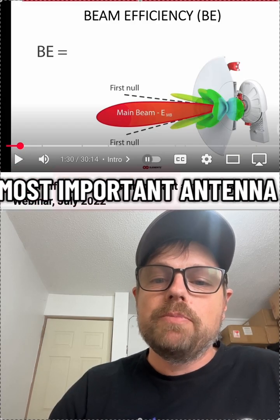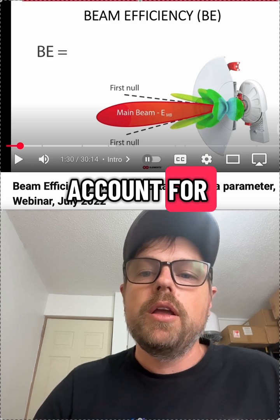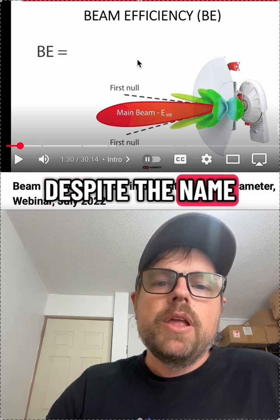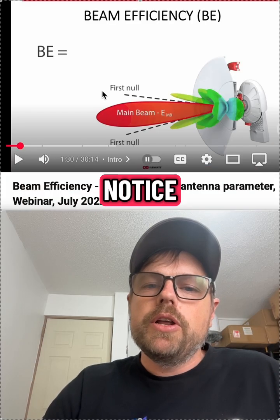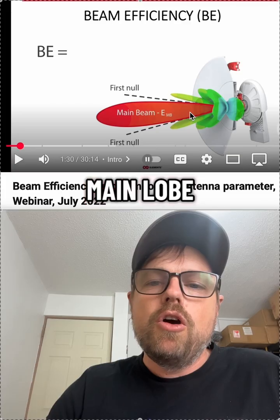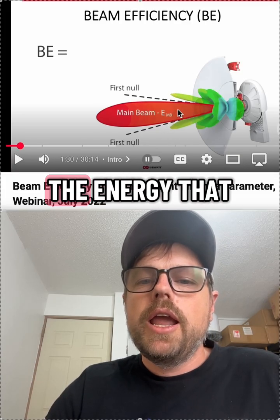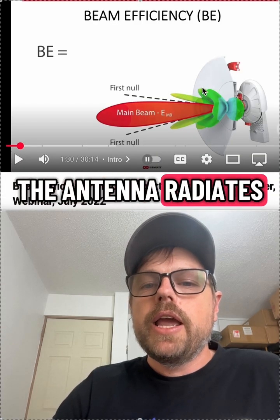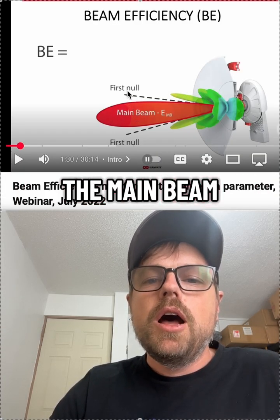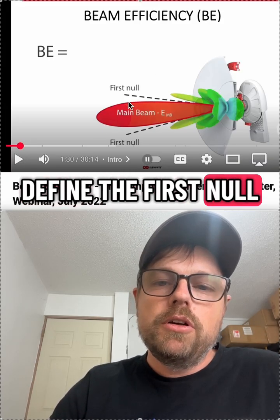Certainly not the most important antenna parameter, because it doesn't account for antenna efficiency, despite the name. The other thing that's important to notice is that they're defining it as the energy in the main lobe relative to all the rest of the energy that the antenna radiates. They're defining the main lobe, the main beam, up to the first null, but they don't define the first null.